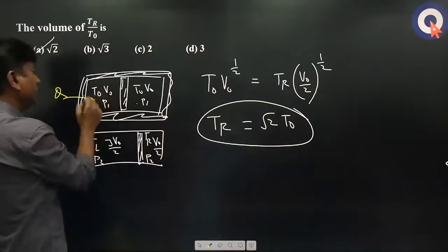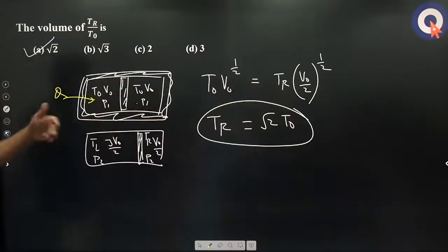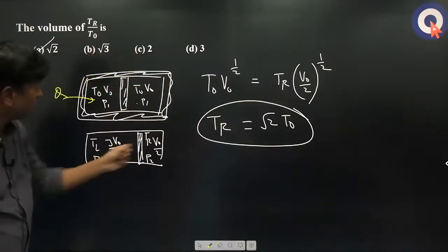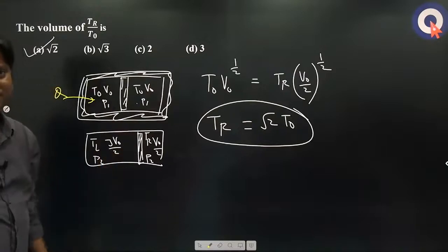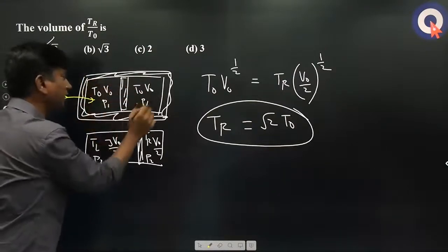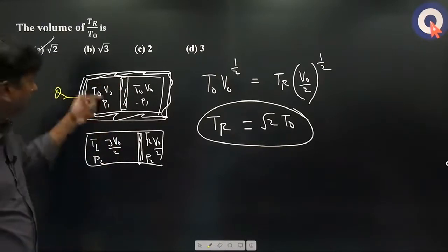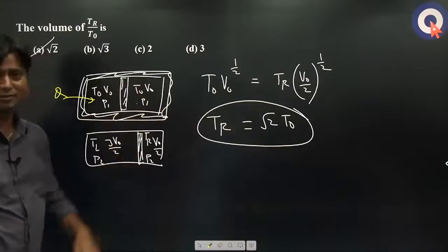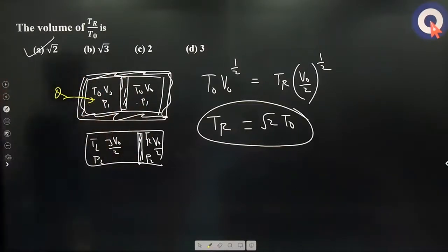So only the internal energy has increased, the internal energy of both sides has increased because of this Q. If you take the total as one system, whatever happens internally is no issue. Whatever heat you have supplied is utilized for increasing the internal energy of both. You may think, sir, it is doing some work. But whatever work it does, the same negative work is done on the other side, so internally this work and that work need not be considered at all.